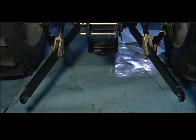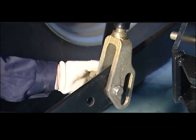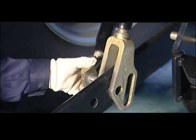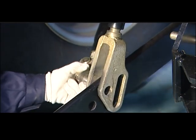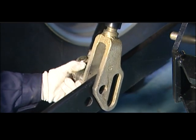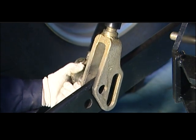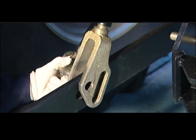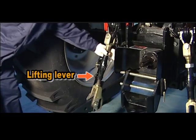Lower pull lever. Lower pull lever and lifting lever are linked by 2 connecting holes, front and back hole. The front hole is usually connected for normal operation, for example plow, etc., while the back hole is usually connected for the implement driven by PTO shaft and large duplex operation implement, such as rotary plow, etc.